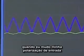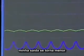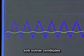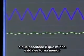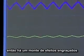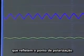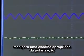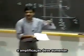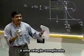As I change my input bias, notice that under certain conditions, my output becomes smaller and gets more distorted. Under other conditions, it's becoming smaller and it's going to get distorted again. So there are a bunch of funny effects happening that reflect on the bias point. But for an appropriate choice of bias point, as I increase the bias, the amplification should indeed increase, and I'll show you that in a few minutes. Yes, but it's a complicated relationship.